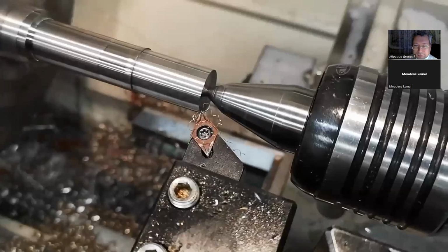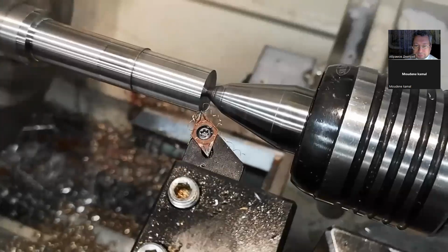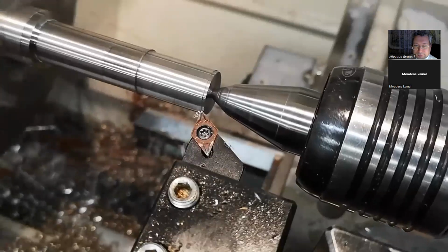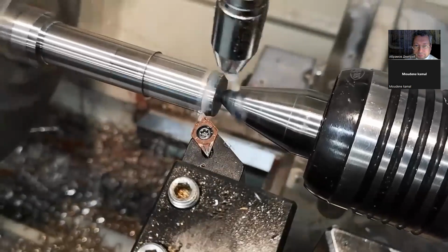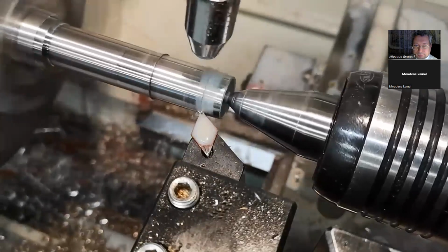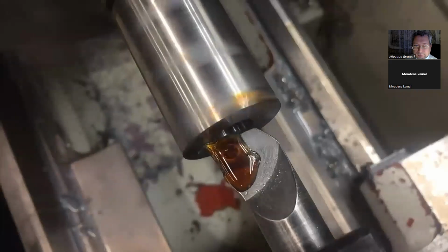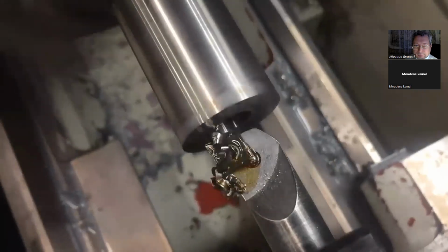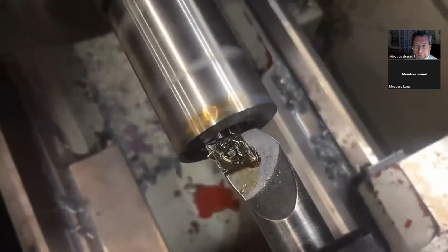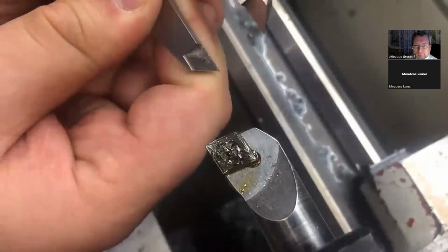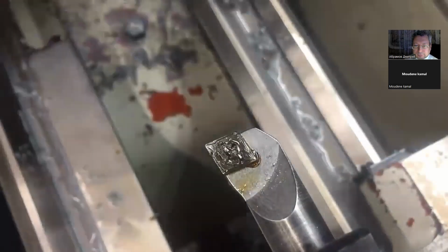Before we get any further, I should mention that I'll be talking about shafts and pins fitting in holes, but per ISO 286, this system can be used for internal and external features of size. You'll sometimes see it used for keys fitting in keyways, for example. How things fit together is determined by how much free space there is between the two parts. If there's lots, there'll be lots of space for the parts to move. If there's only a little, there'll be a lot less space. Finally, if there's no space, the part won't be able to move.